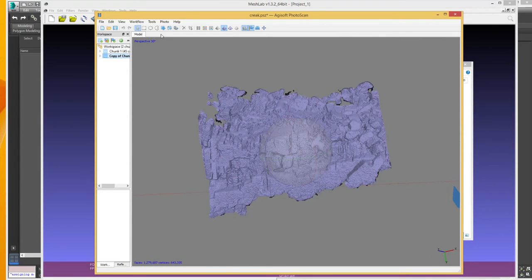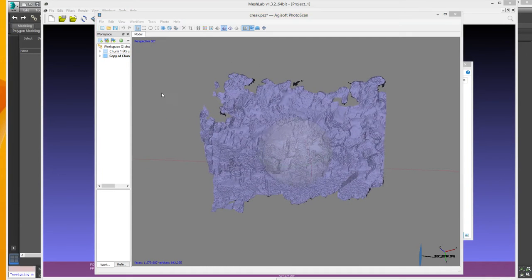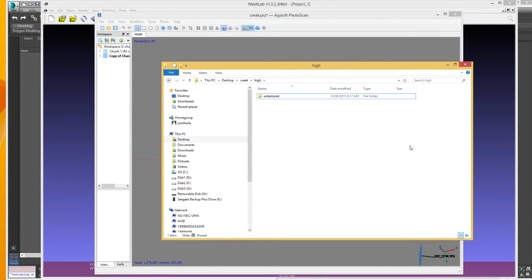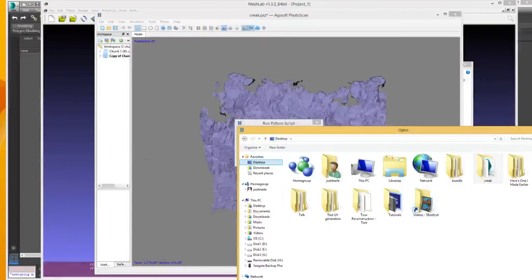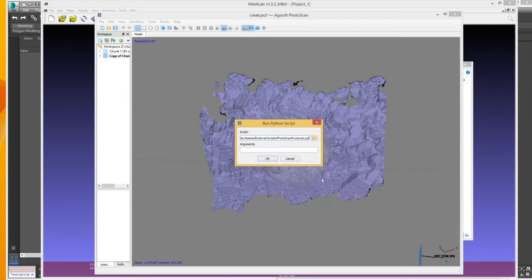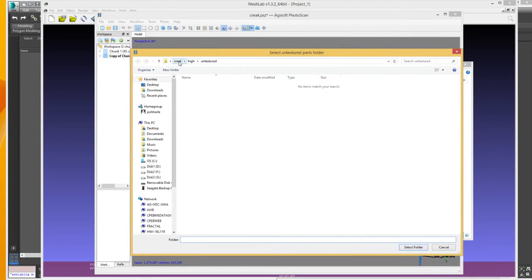Since we're using the Pro version of this software, we don't need to do that. What we can do is go to Run Script. Actually, I'm just going to delete that textured folder that I just generated. We go to Run Script. We find the SiteViewer project folder, go to Assets, External Scripts, PhotoScan Pro, and it's just imaginatively called script.py.